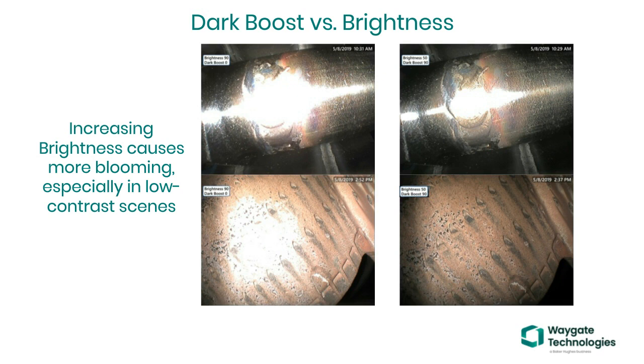Notice how more of the heat-affected zone and weld toe is apparent in the right weld image in the top left. Also, because in stereo measurement, pixel matching is so important, dark boost can be a way to get a more measurable image. Let's look at another example on the next slide.